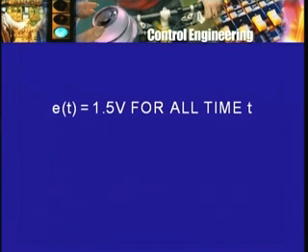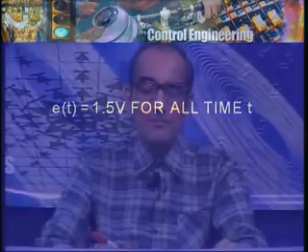And once again, we know that this model can cease to be good. If you use a cell for a long time, then it doesn't behave like this anymore. If you actually measure the open circuit voltage of the cell, you will find that it's not 1.5 volts, but it has come down to 1.4 volts or even less. And not only that, when you actually use it in a circuit, so when you have current in it, the voltage may be even much less than 1.5 volts.